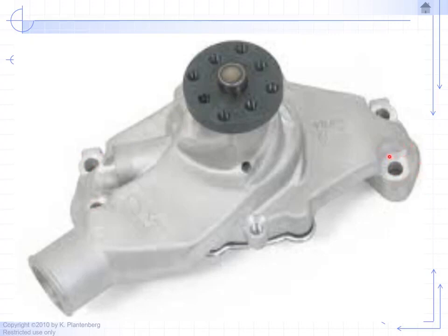So you come in and drill your first hole, then you come in with your second hole, the counterbored hole, and you drill, and it's going to remove some of that rough surface with contours. So you're guaranteed to have this surface parallel to the base. Same thing with the other four. You have the top surface of the counterbored hole parallel to the base.